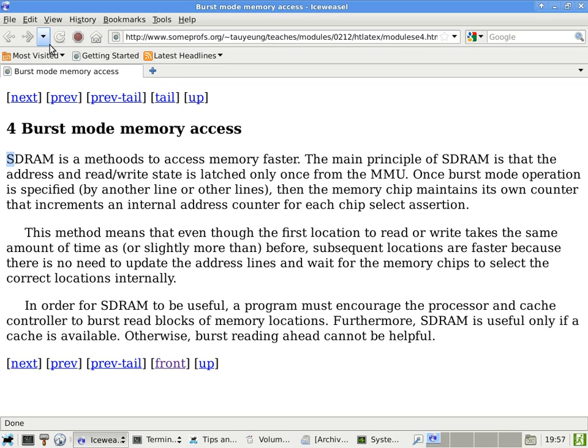Are there any questions on this slide? This is stuff that we already talked about. So, since you can't increase the clock frequency, that's why you just sample at a higher rate? You can increase the clock speed. It's just that the clock has to feed multiple chips, and as a result, you cannot change the frequency of the clock chip as easily and just crank it up. Yep.